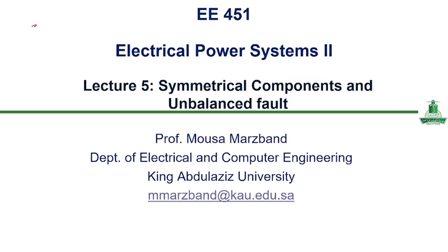Okay, today I would like to continue our discussion with lecture 5, which focuses on symmetrical components and unbalanced faults. In this lecture, I will explore how unbalanced three-phase systems can be analyzed by using the method of symmetrical components. This powerful analytical tool allows us to transform an unbalanced system into three balanced sets of components, positive, negative, and zero sequence, which greatly simplifies the analysis of complex fault conditions.